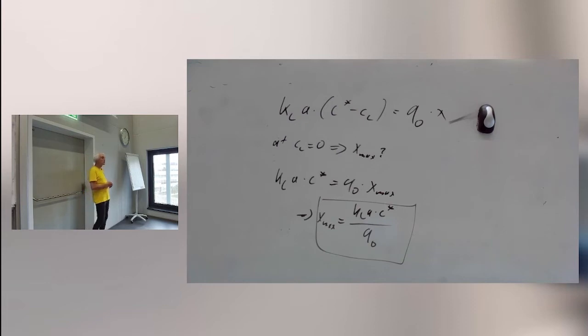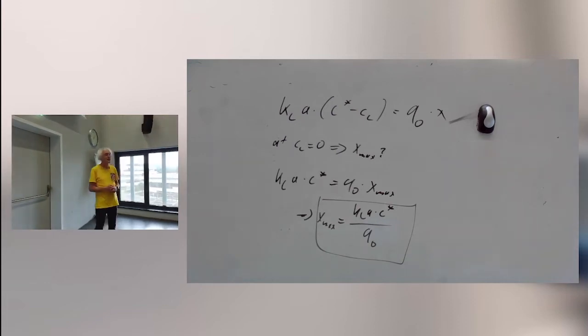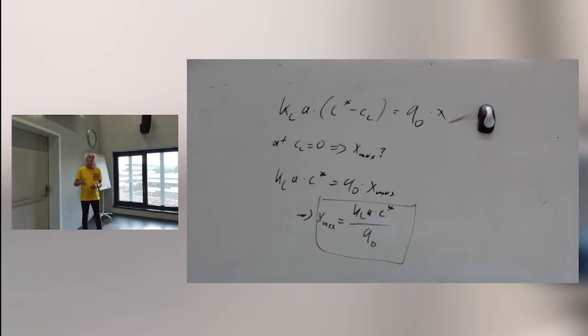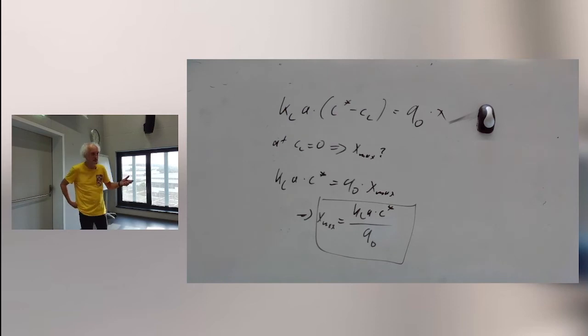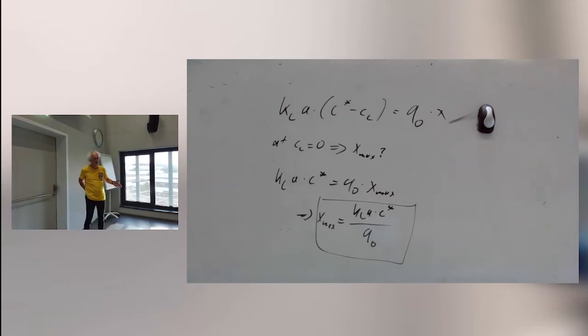Okay. So of course you could switch to another substrate. You could use nitrate as electron acceptor. We talk about bioprocesses here. Yeah. So if we design a bioprocess with oxygen, we don't at the same time put tons of nitrate in our bioreactor because we say, maybe the KLA won't be enough if we want to grow. Yeah, but on nitrate, if you switch from oxygen to nitrate as an electron acceptor, your growth rates will go down. Yeah, they're lower. So this is something you don't do. Therefore, you use oxygen. There must be a reason.